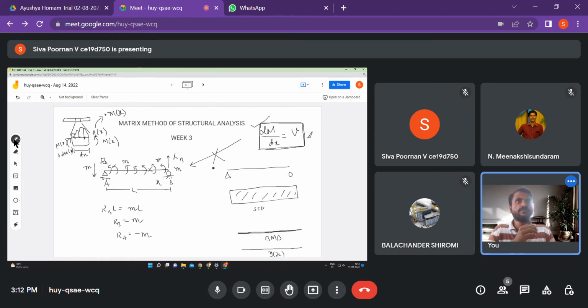Okay, that is the whole point. This thing is valid only at points where there are no external moments applied onto it. So therefore, we cannot say differentiation of moment is equal to shear force for this beam because it has entirely distributed moments onto it. So that answers the second question. What happens to the first question? First question is, what is the deflected shape?